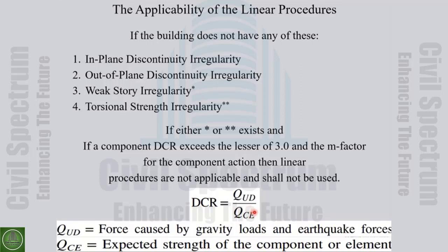We use the same equation that we have for calculation of the bending strength of a beam. But the values for the material, Fy and f'c, will be expected values for the deformation control parameters. For the force control parameters, they will be lower.